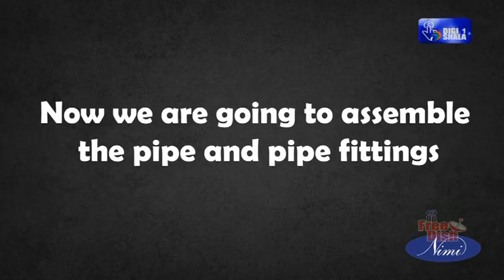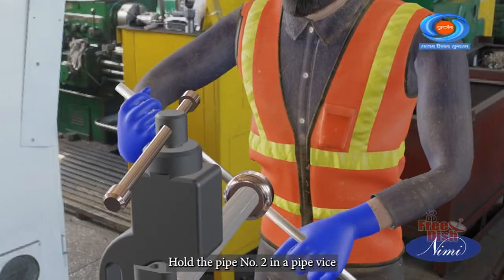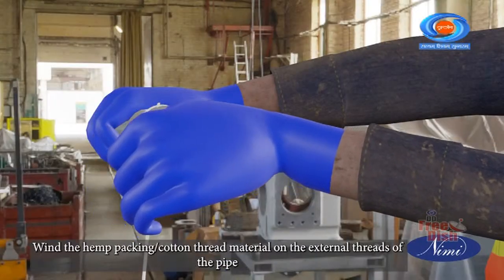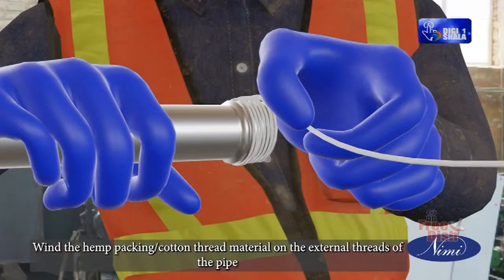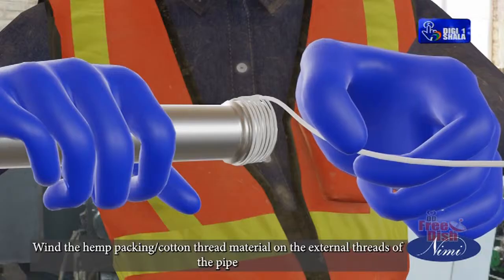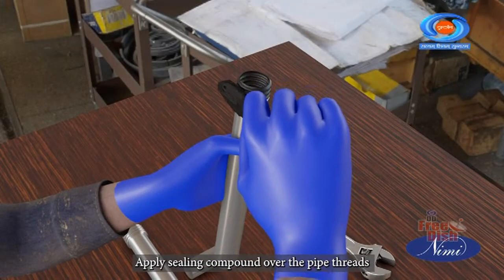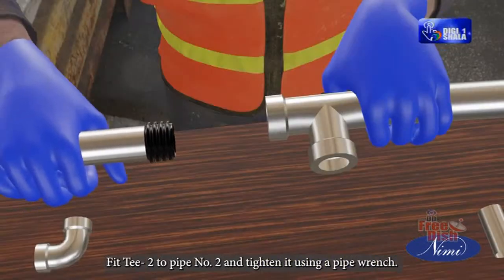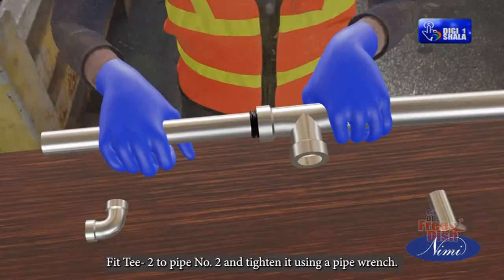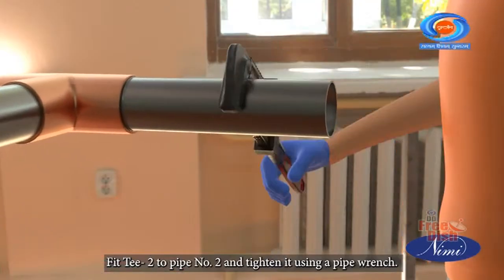Now we are going to assemble the pipe and pipe fittings. Hold pipe number 2 in a pipe vise. Wind the hem packing or cotton thread material on the external threads of the pipe. Apply sealing compound over the pipe threads. Fit T2 to pipe number 2 and tighten it using a pipe wrench.